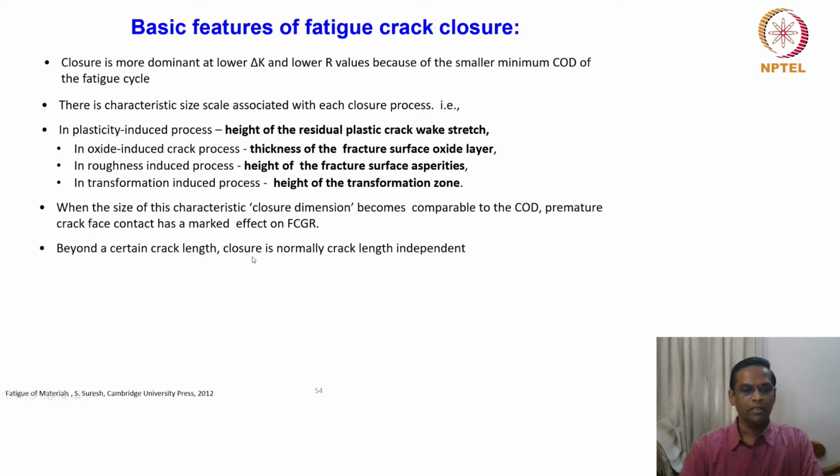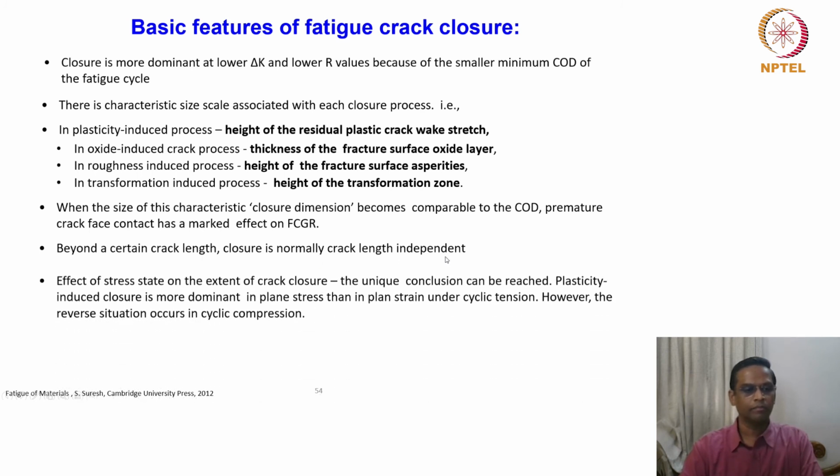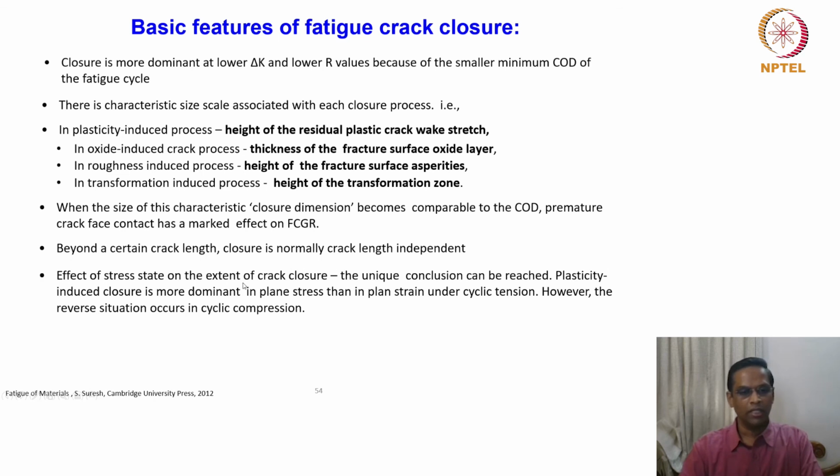Beyond a certain crack length, closure is normally crack length independent. Effect of stress state on the extent of crack closure: a unique conclusion can be reached. Plasticity induced crack closure is more dominant in the plane stress than the plane strain under cyclic tension. However, the reverse situation occurs in cyclic compression. So this is one important effect of state of stress on the crack closure.